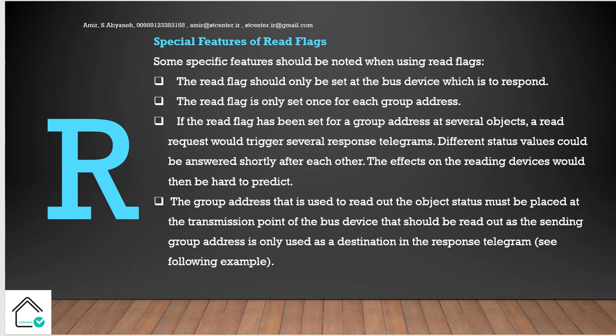The next important note is that the read flag is only set once for each group address. It's very important. In one group address you may have several group objects, but only one of them should be set with the read flag. You never ever have two group objects with the read flag on in one group address. Remember that.